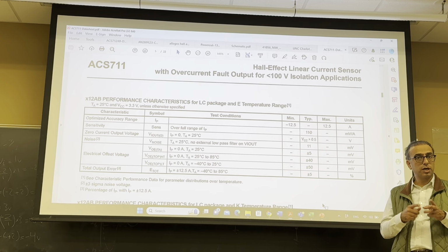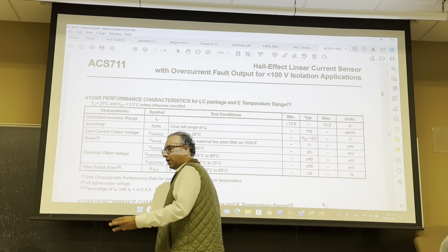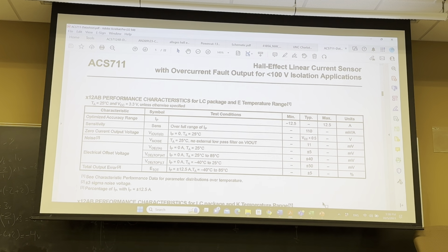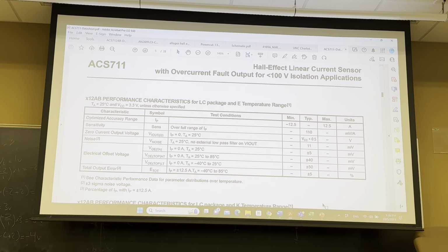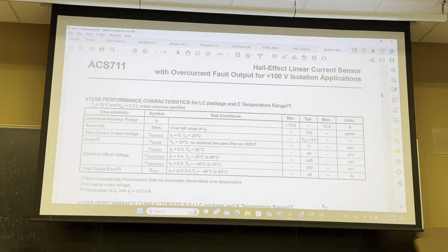Again, you need two circuits: one current sensor circuit for AC side measurements, and you need voltage measurements at minimum on the DC side, right? But in general, we measure DC current, DC voltage, AC current, and AC voltage in practice.